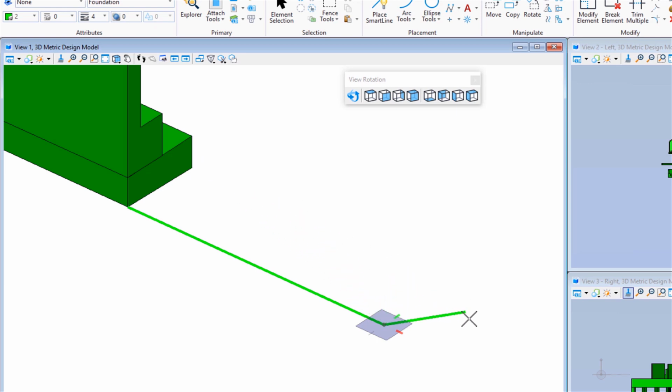Now I'm going to move my cursor in this quadrant near the green tick mark, or the compass's y-axis, and on my keyboard, hit the Enter key. And when I do that, you see it jumps to that axis nearest my cursor. To unlock it, I hit Enter again, and I've unlocked it. I'm going to lock it, hitting Enter. I'm now locked on that axis.